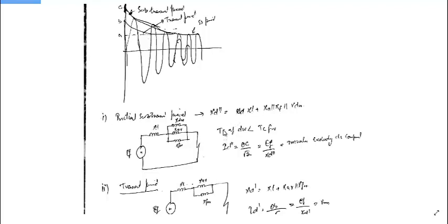So you will see that, since I have explained that the time constant of damper winding is less than the time constant of field winding, this ID double dash will be equal to this OC. OC is this envelope, here to here, OC divided by root 2. This will be the RMS value of the initial subtransient current. ID double dash will be the initial RMS value of the subtransient current. This is the current that flows through this synchronous machine in the subtransient period.